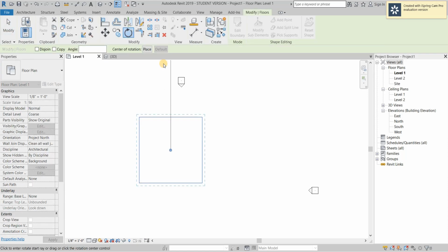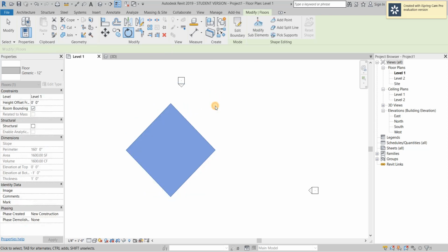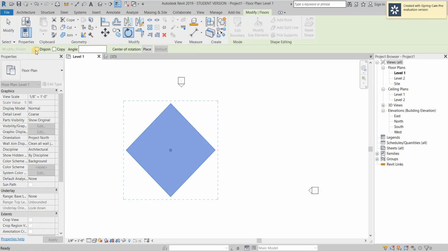You can rotate it. When you rotate, it automatically will rotate from the center of whatever object you have, and it will tell you the angle and degrees you're working with. If you wanted to rotate from a different point, click your object, you go to rotate. Up here will be a little panel where you can type the angle you want to rotate. Maybe you want to rotate and copy it, or you want to place your center of rotation somewhere different. You will type place. You can click to where you would like, and then rotate just as usual.